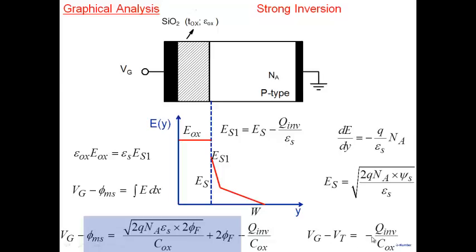So it says once you cross the threshold voltage, inversion charge changes linearly with the gate voltage minus the threshold voltage. Yes, which you have seen, which we had derived in the notes itself. But we have looked at it from another angle, which is through a plotting of the field and then integrating the field here.